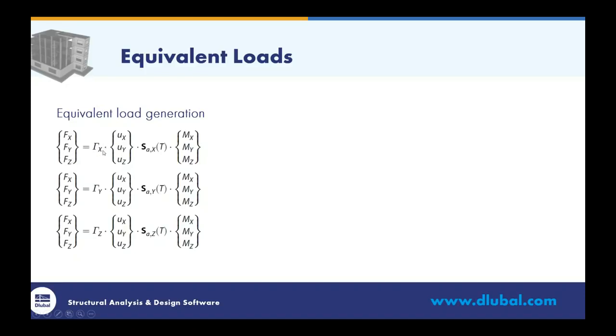Now, over on the right-hand side, we have some additional variables, such as the participation factor. We have our mode shapes available to us here. S sub A would be the acceleration from the ASCE 7 response spectra as a function of the building period. And then we have over on the right our masses. So we have all of these different mode shapes, and in our project today, we have 10 different mode shapes. So the question is, how do we combine all these different mode shapes for each excitation direction? And this is where we have one of two options.